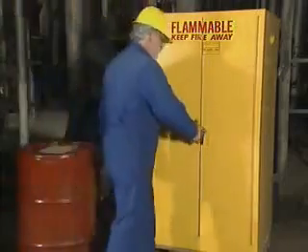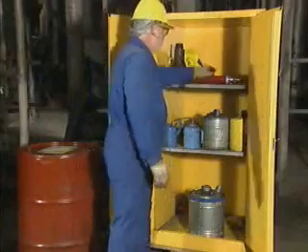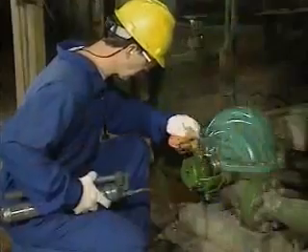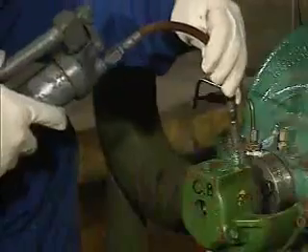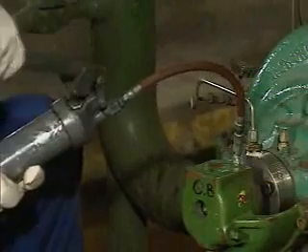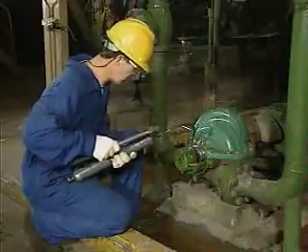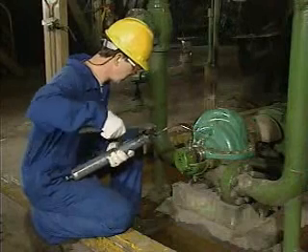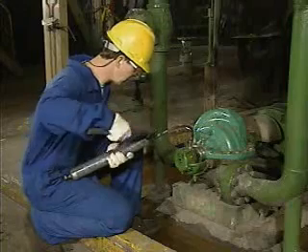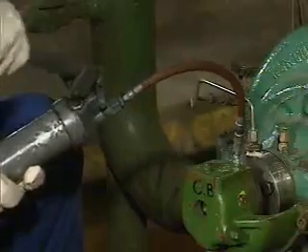In this part, we'll look at common types of lubrication equipment for industrial applications. We'll begin with a grease gun. Hand-operated grease guns, or lever guns, are often used to grease bearings. Typically, the nozzle end of the gun is attached to a grease fitting on the bearing housing, and the gun's hand lever is pumped to apply grease through the fitting to the equipment's bearings. Grease guns enable you to develop high pumping pressure with little effort.